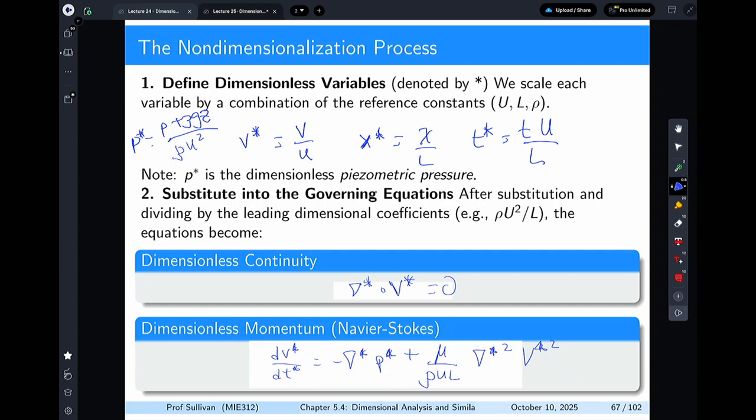Now, in all of these cases, especially as mechanical engineers, we always deal with non-dimensionalized velocities, non-dimensionalized acceleration, non-dimensionalized pressure gradient, and here I have 1 over Reynolds number based on some sort of length scale. So all those terms come out, and it works really well.